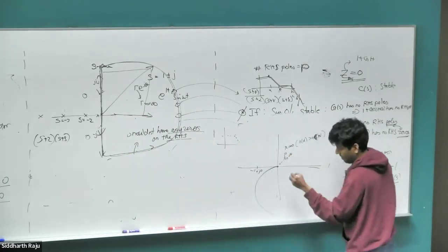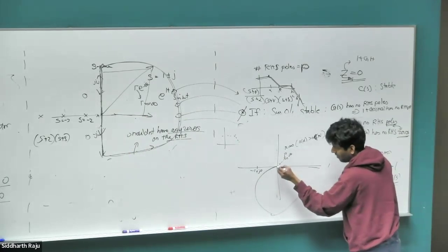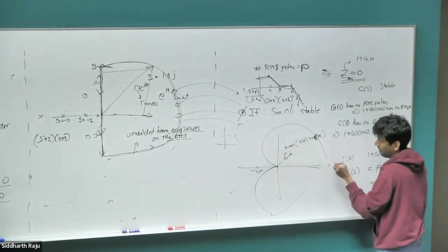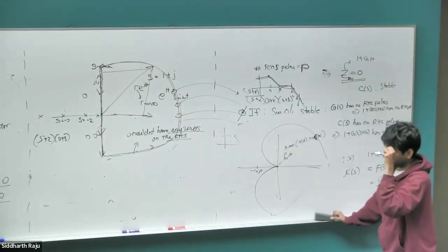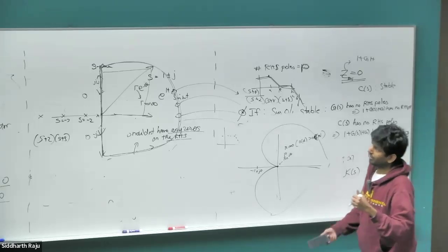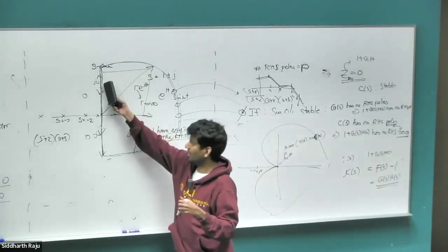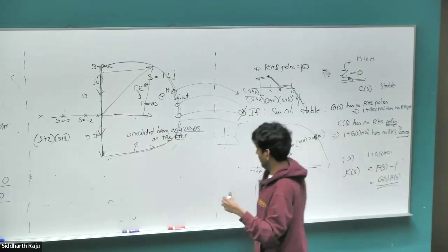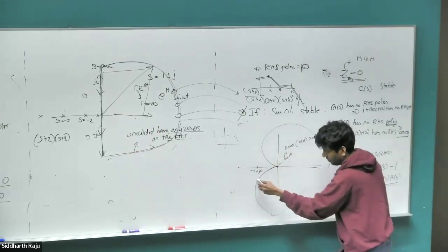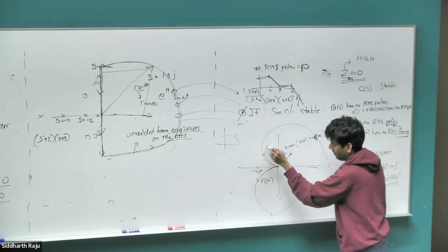So whatever graph I have here, this will have looked like some waveform. It will just be the same one with the symmetric nature, right? Because it always appears as complex conjugate. If I have j omega here, this is the complex conjugate, negative j omega. So whatever plot I got here was for f of j omega, and this plot would have been f of negative j omega.